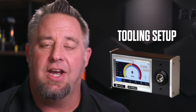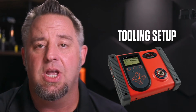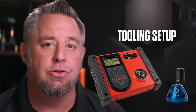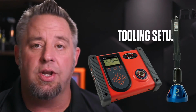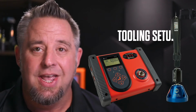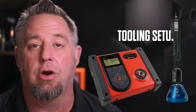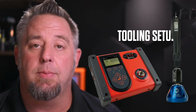If we look at the different types of tools we would use with that, it would be a torque analyzer with an internal transducer. We could also use a different type of tester where we can add additional torque sensors to that, or we could use that for hand tools. We could also use that for power tools. And here's an example of the tool with a rundown adapter on it to help simulate the actual rundown of the part. This is just an example of ways that we can use the torque analyzers to help set up our tools and make sure that they are producing repeatable results within the torque tolerance that we may need.